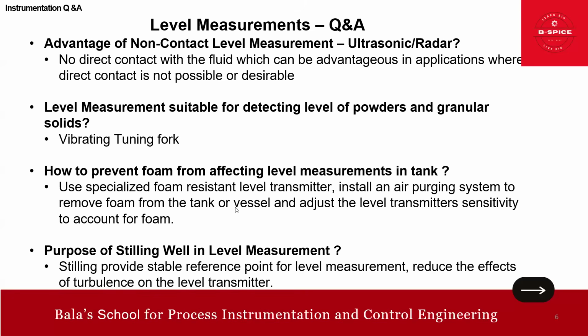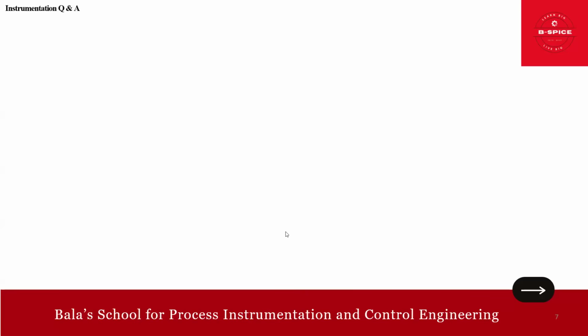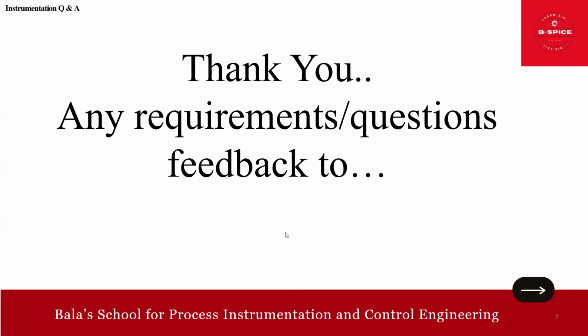Okay. Then, what is the purpose of a stilling well? Yeah, I just told you, right? Yes. So the stilling well provides a stable reference point for the level measurements, meaning it reduces the effects of turbulence on the level transmitter. Foam or turbulence, all these can be gotten rid of using a stilling well. So these are some of the questions that just came to my mind, friends, on level measurements.